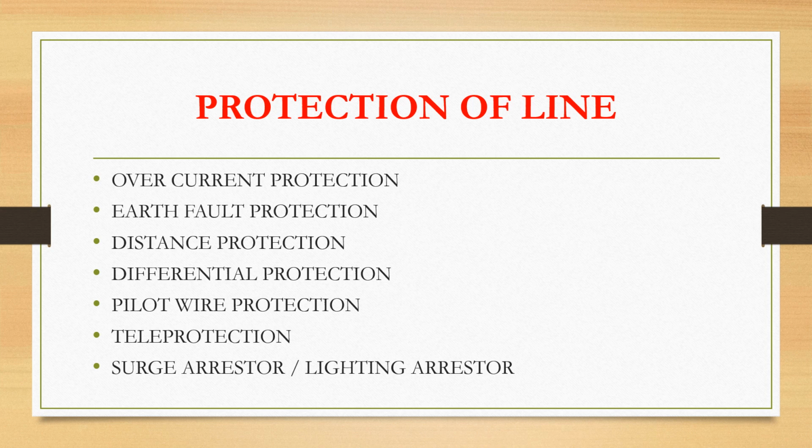But the problem is that when we talk about the extra high voltage system, which is basically operated in a ring fashion, and different kinds of generators and regions are connected through the transmission lines, then these relays alone cannot cover all kinds of faults, especially when the direction is required. Plus another flaw is that these overcurrent relays have just one quantity to sense for the operation, so they do not look into the other quantity, which is